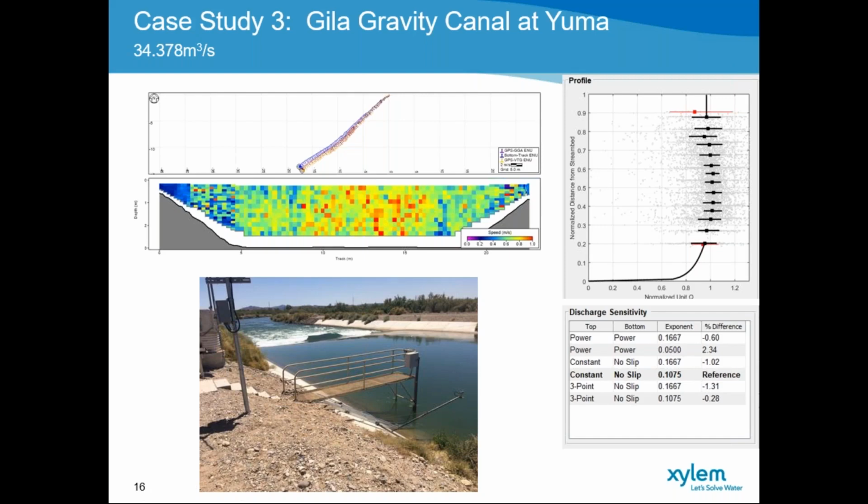There are two factors impacting this specific site, which is very common with a lot of irrigation sites. There's the actual control upstream created by the cofferdam that wasn't removed, so there's an acceleration of the flow there. As well, during peak releases, this gauging weir is submerged almost 100%, so your velocity distributions change depending on the flow releases in the channel. So it is important, especially at this specific channel, to verify the extrapolation with almost every single measurement exercise to make sure that the correct extrapolation is applied.